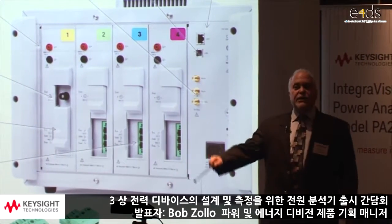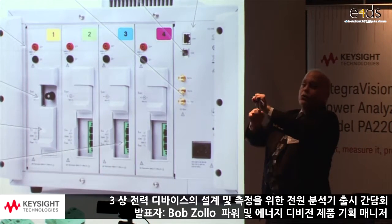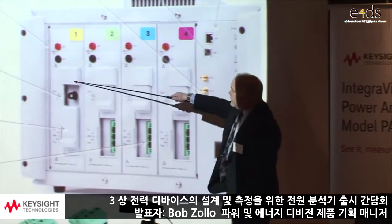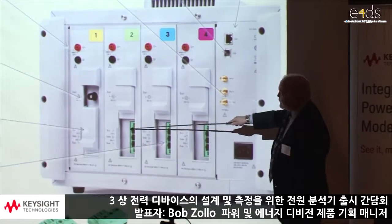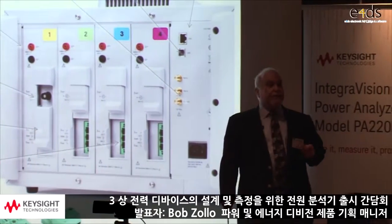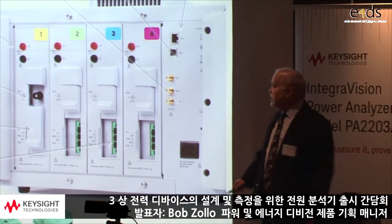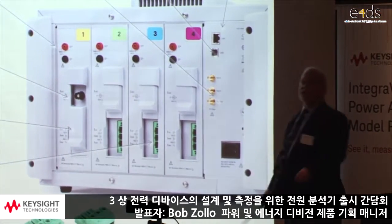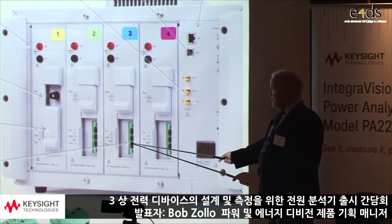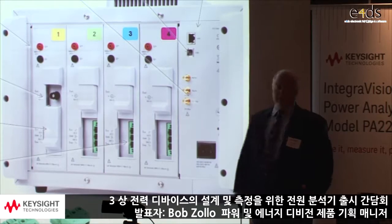Sometimes it's easy to make a current measurement by, if this is the wire, clamping around the wire. And the clamp will tell you how much current is flowing through the wire. Or I can slide this little door up, and it exposes this green connector, and now this is like an ammeter that you'd find on a DMM. That means you can run the wire in and out of this connection, and it has an internal current measurement system, which is extremely accurate. So this is for ease of connection, and this is for highly accurate current measurements.